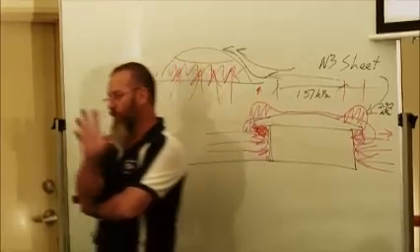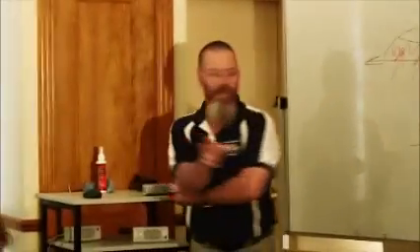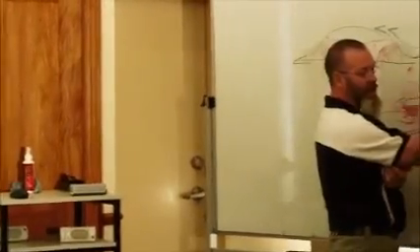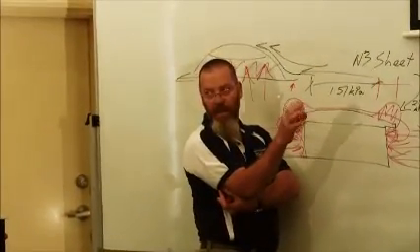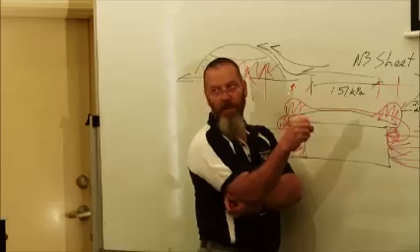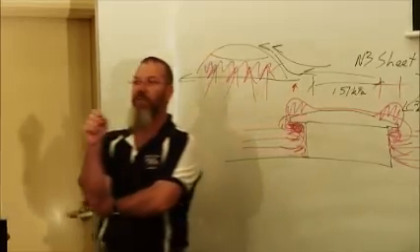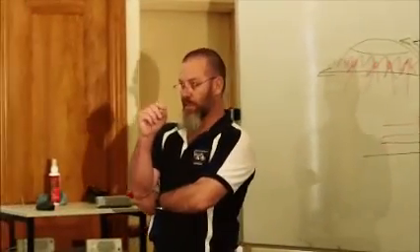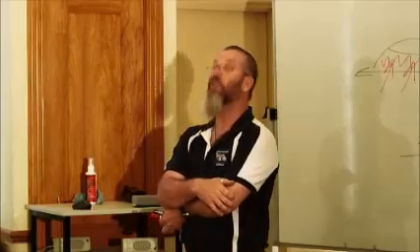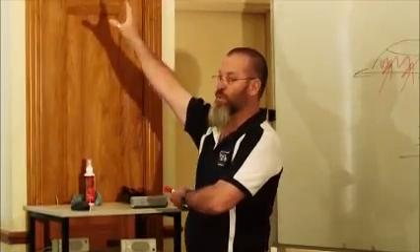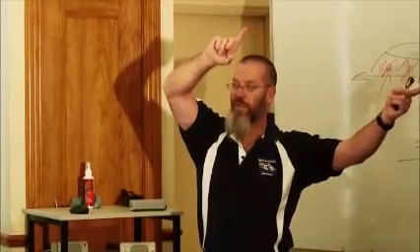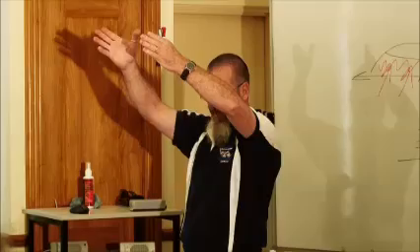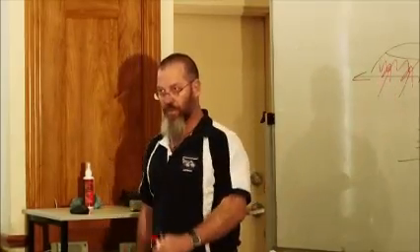If you think about it, the area surrounding a batten connection out here, let's say our battens for a tile, for a sheet roof are at 900 centres, okay? They're 900 centres over here in the edge area, and they're at 900 centres over here. So the area is the same, okay? You will get some cases in some industrial buildings where I was standing at the Big Green Hardware store the other day, looking up at the purlins on the roof, and over towards the edges, because they had them out here at 1.5 metre centres, over on the edges, they had them at 750 centres. Thank Dr. Bernoulli for that.